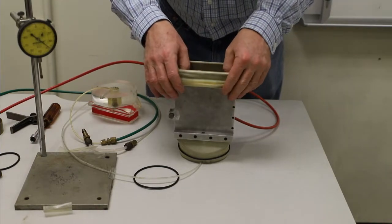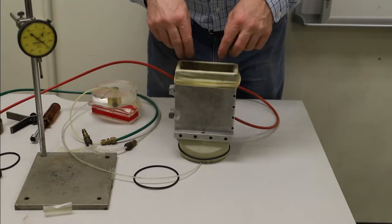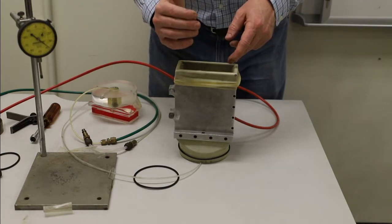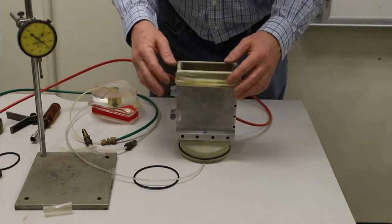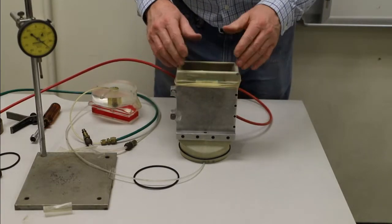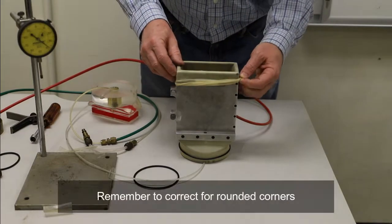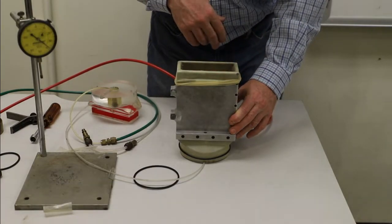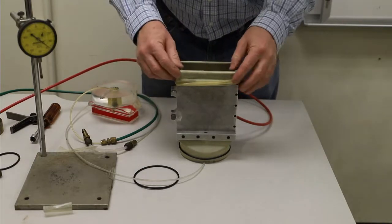We want a nice smooth surface, and as you can imagine, when you try to put a membrane into a square corner, the membrane wants to round a little bit, and the vacuum is trying to pull it out into a more square shape. But we'll have to adjust for the fact that, especially once we take the mold off, we're going to have round corners, and we're going to have to account for those. So looks like the biggest radius is on this hinge corner, and there's not a whole lot I can do about that.